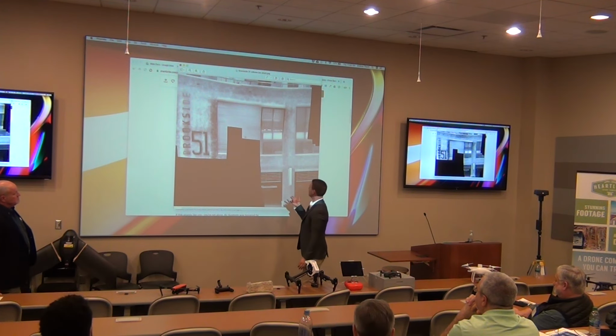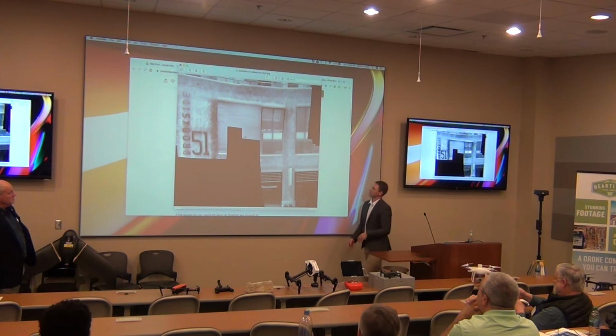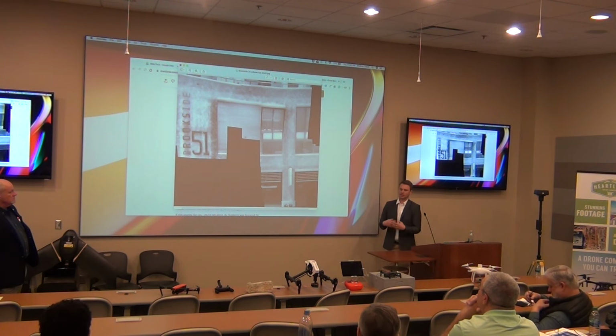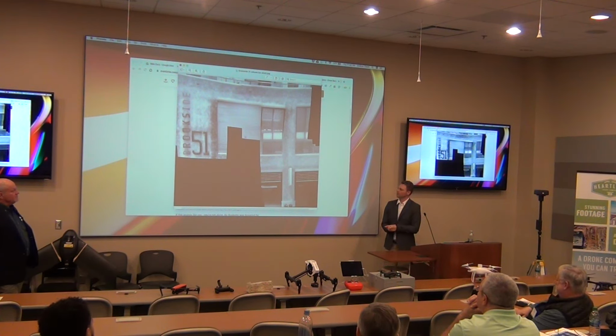So what we can come away with are these blotchy areas, and if it's a darker blotched area, that means the stone is more cool, in essence, and that is an area that you definitely want to go up and intrude, because it might actually have an air gap behind it or a void. So that's how we were able to pinpoint certain areas and then go up and do tap tests around that and then truth the data.